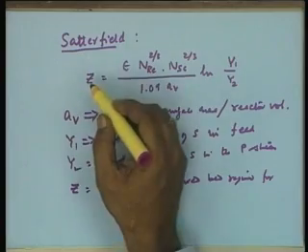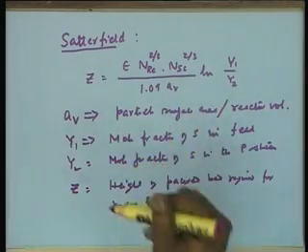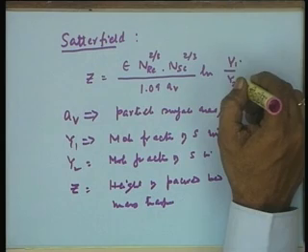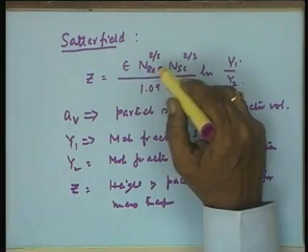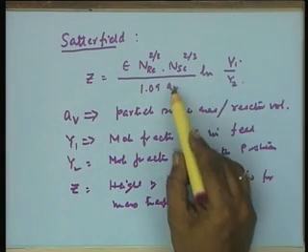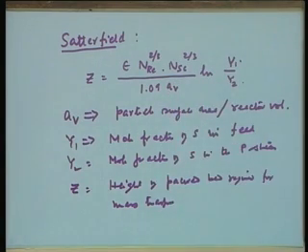So, basically and purely on the basis of mass transfer control, no biochemical reaction is assumed here. As if the mass transfer has to be incorporated, this much length of the reactor is required under these operational conditions to have the substrate concentration reach equivalent to bulk. That means, to make Sb minus Ss equal to 0 without any biochemical reaction, this much height of the reactor is required under these operational conditions. Now, obviously, based on the operational data, that means the concentration of substrate in the feed and the product stream, as well as the parameters of the reactor operation and the particle morphology, the particle size, one can determine the length of the reactor required,